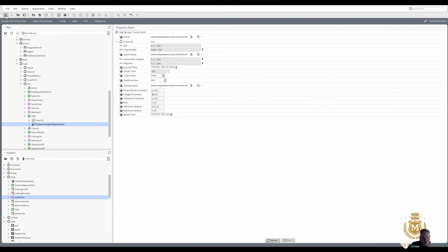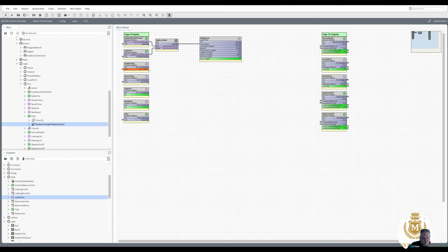And let's put in our supply temperature, which is what we're going to supply out to the building, into the room. So that's our control variable and our set point. Now we can put the 21 straight into there if we want to, but we want a dead band between heating and cooling, so I want to give it a dead band. We'll come to the dead band in a minute.